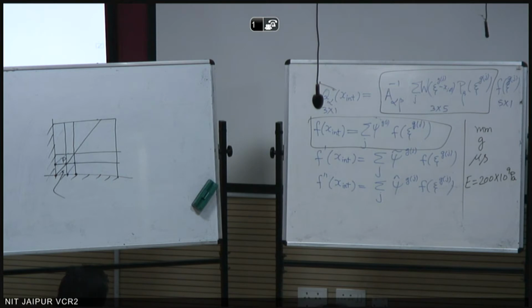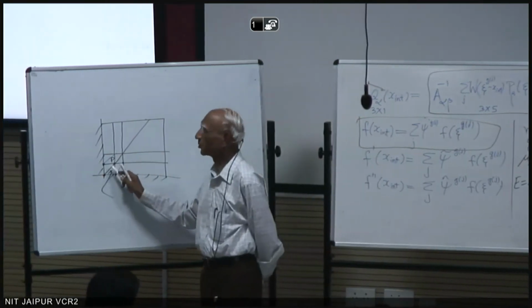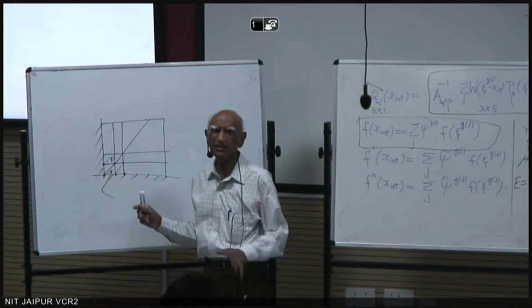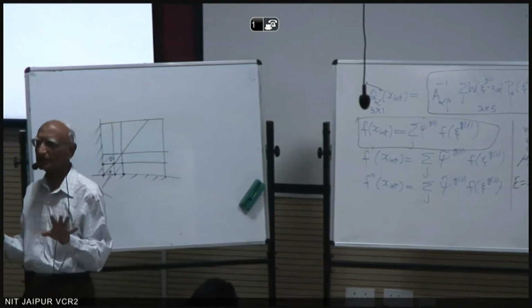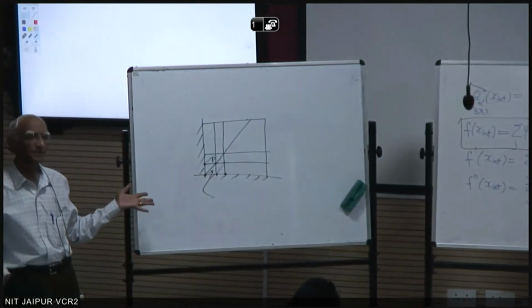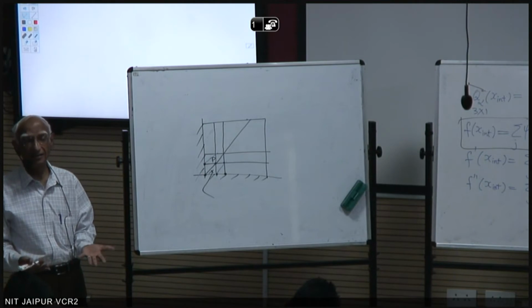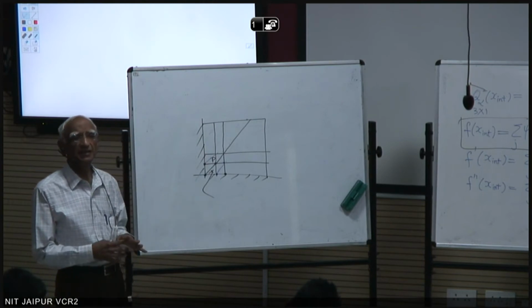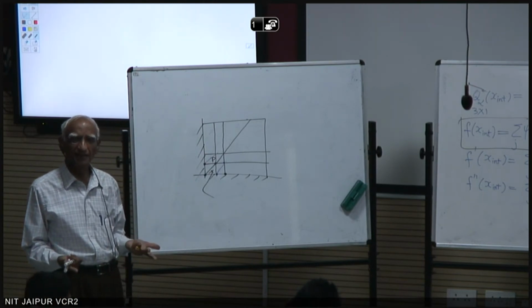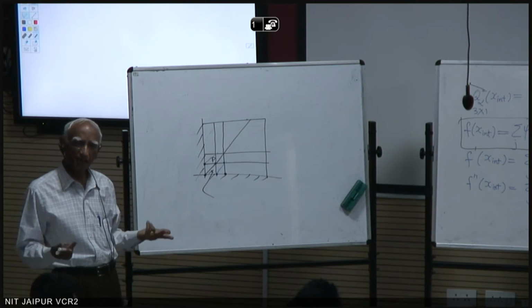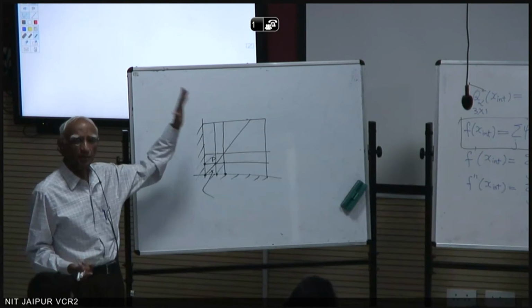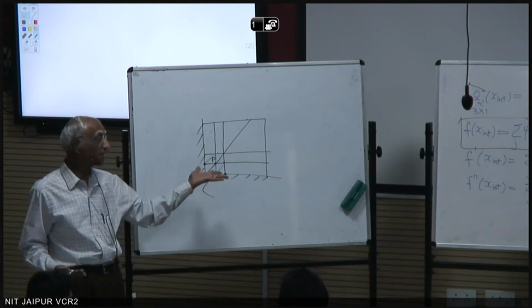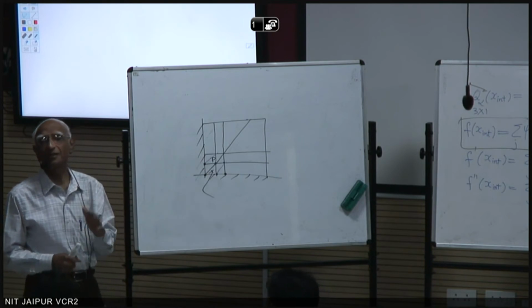That way, that constraint won't show up. Like if I change my mesh so that I don't have some well-structured mesh. These are cooked up examples, so I'm not saying that you are going to use a mesh like this. But if you did, the point is, for an incompressible material, a mesh like this will give you zero displacements everywhere. And therefore, I'm applying a million PSI load, and nothing is moving. That's because the mesh is like that now, and has a constraint.